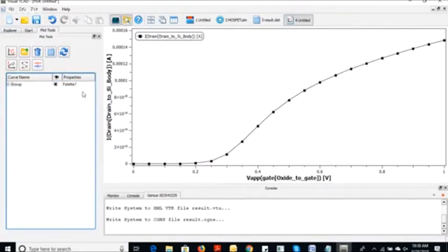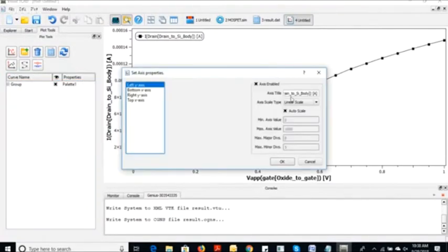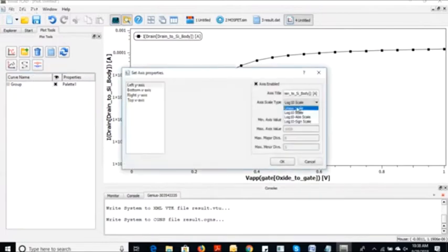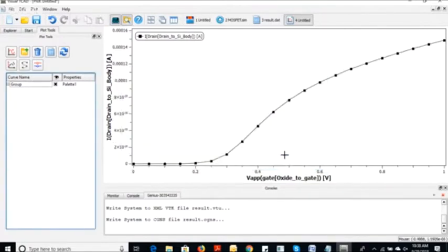We have an IV curve. Our leakage, our off current, is in this nanoampere range. On is this. Okay, log scale, linear scale, and threshold voltage is approximately 0.2, in between 0.18 or 0.2 volt. Now we want to see how the channel is forming.